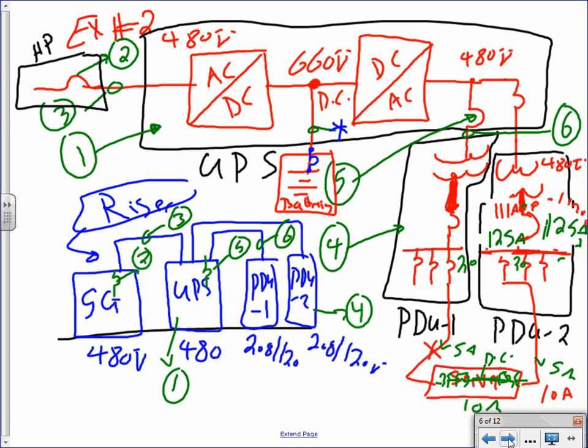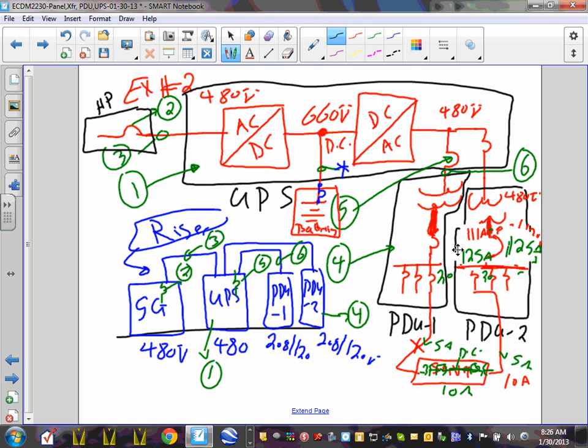Now, my expectation from you guys for the project that you did is that you're going to size the transformer to feed the receptacle panel exactly the same way we size it, the primary and the secondary. Okay? So when we do the red lines and you ask me how am I going to size this, Chad, that's how I'm going to size it. The same thing, guys, for the bus duct 28120, same way. When you need a transformer to feed the bus duct, we'll size that transformer the same way. Okay, let's take a 5 minute break.